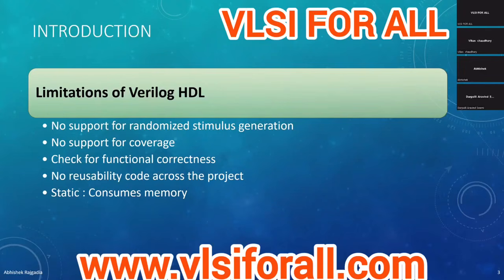So you need a concept like randomized stimulus generation. Let's consider an adder, a 2-bit adder. There are 2 input signals, A and B, so the total combinations are 4: 00, 01, 10, and 11. But consider a GPU, you can't even imagine how many combinations there will be. So it's not possible to test every combination of a complex IP. For an adder, 4 combinations you can test right away, but not for a complex IP like a DDR or a processor or a GPU.